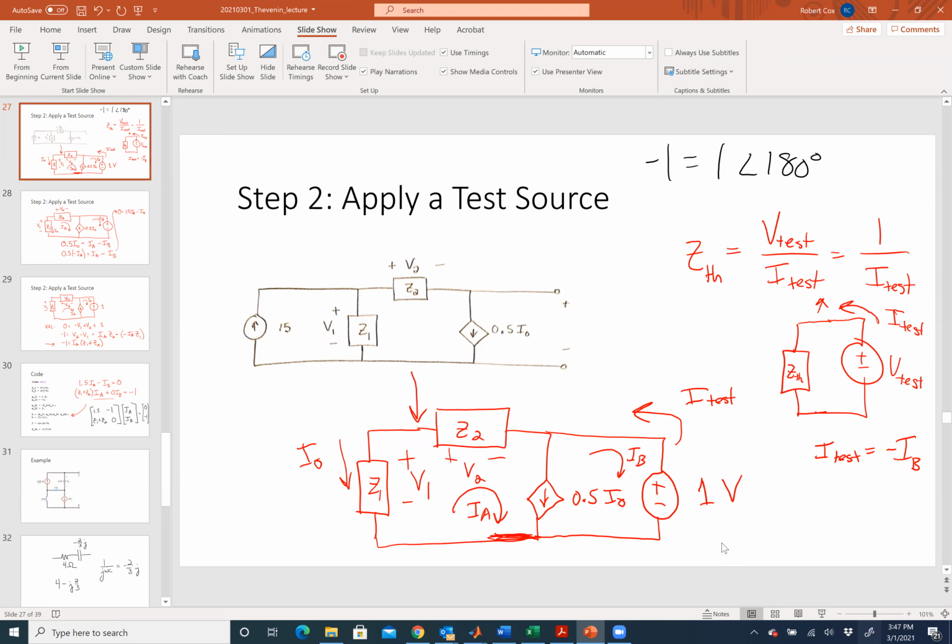See, they share a terminal, but they don't share a second terminal, right? So the voltage across them is not in parallel. Voltage across 2 elements has to be the same for them to be in parallel. That current source is screwing this up in this case. Right. The voltage across the current source isn't necessarily 0. It has some voltage. We don't know what it is. The circuit tells us what it is.